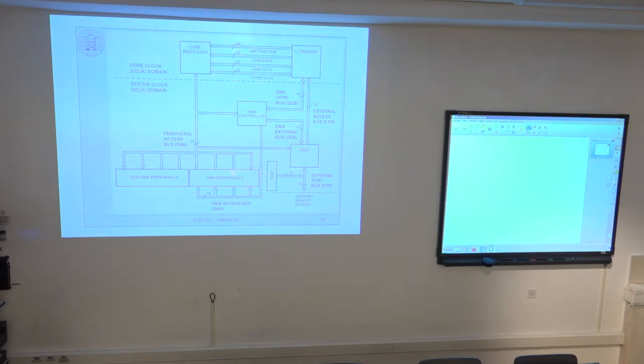The idea is some of those peripherals which have high data throughput, high data rate, they are supported with a direct memory access controller in a way that automatically DMA can address these peripheral ports, do the fetching, and write the new value into a memory buffer automatically without any intervention from the main CPU.